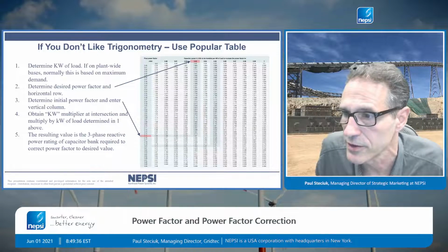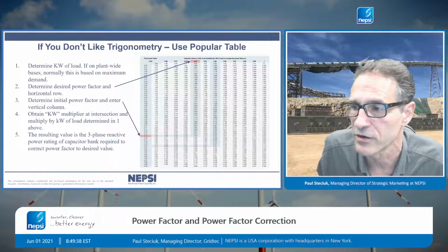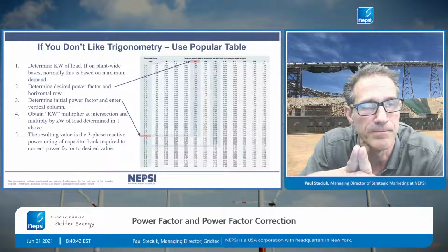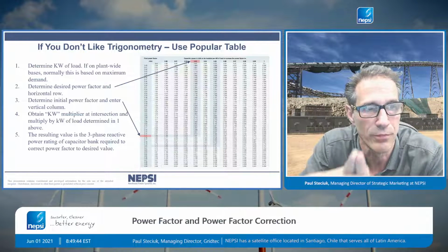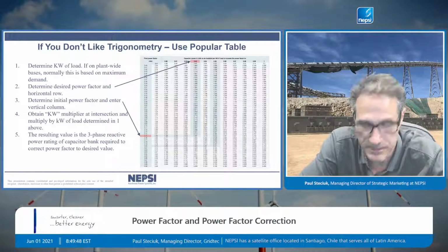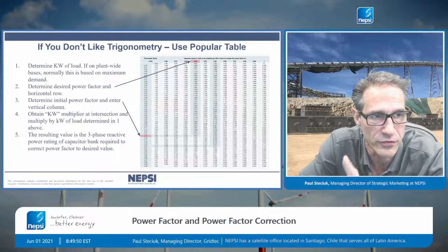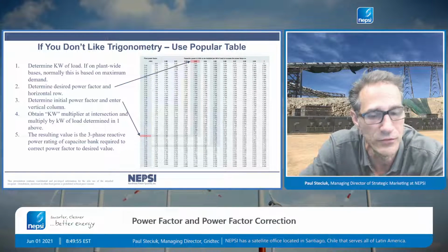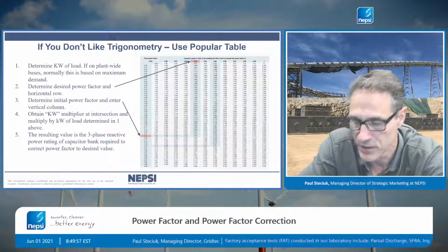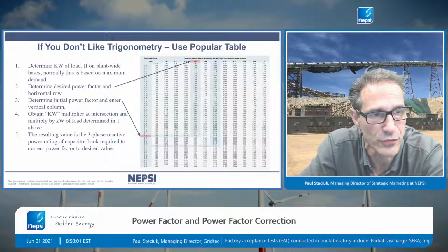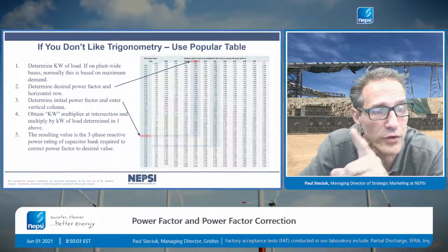Somebody's asked me, can you explain once more the power factor correction with harmonic filters? So what I'm saying is harmonic filters are applied for 3 reasons. Number 1 is power factor correction. Harmonic filters are installed for power factor correction. Number 2, you install filters for the prevention of resonance, or to preclude resonance.